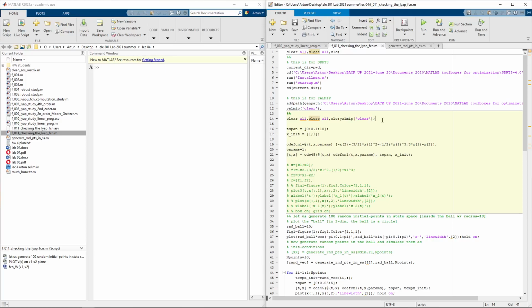We imposed these constraints and parameterized the Lyapunov function, and basically covered how you would compute it. We showed how you would select some basis functions like first order, second order, etc., right? And then we covered how you would use SOS methods, and in the previous lesson, linear programming, right? Linear programming is another technique of computing Lyapunov functions.